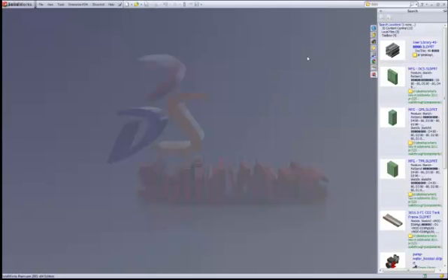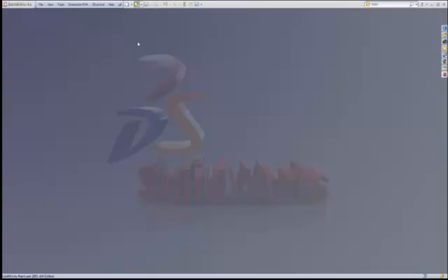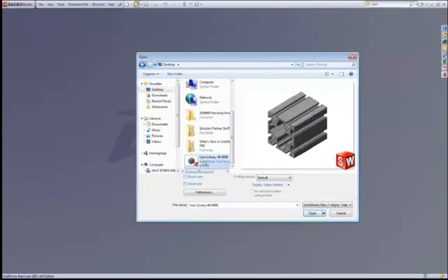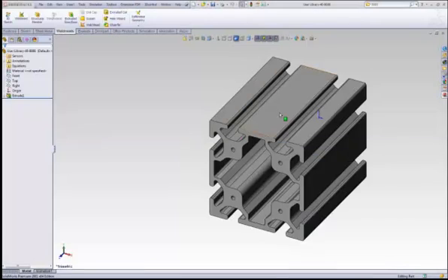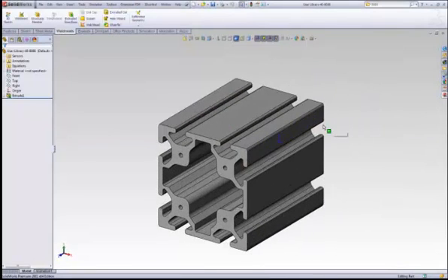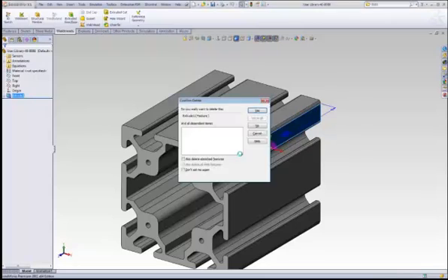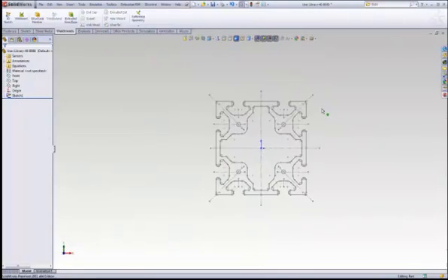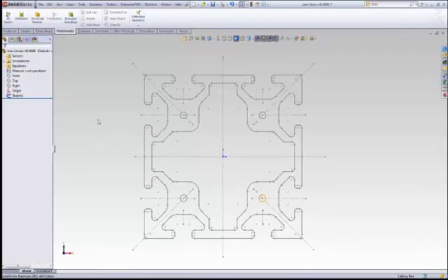Now, I'm not going to download this one. I think I'm just going to open an existing one. Actually, I did download this one, but I don't want to download it now. All we need is the sketch. So I'm going to delete the extrusion, and I'll go ahead and look normal to that. The default location of your tube is going to be where the origin is on that sketch. And so you could change that if you want to move the sketch around, if you want to edit it.